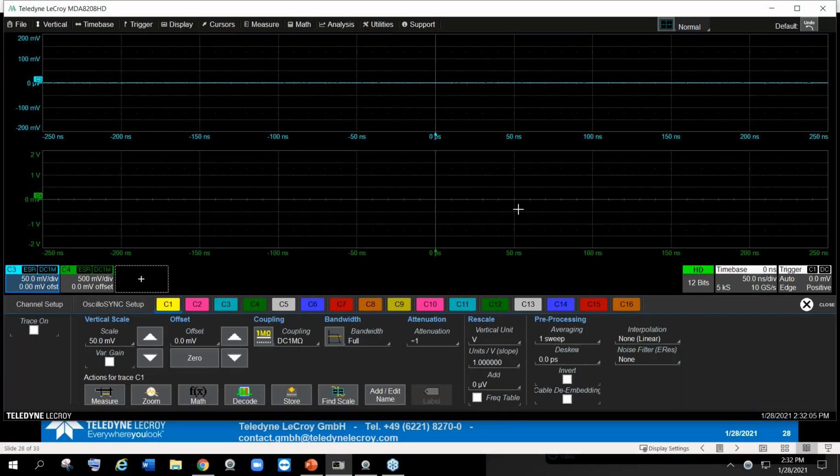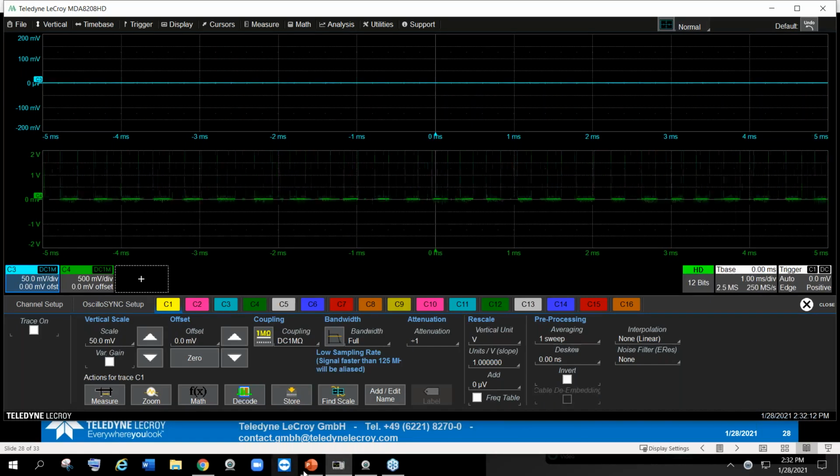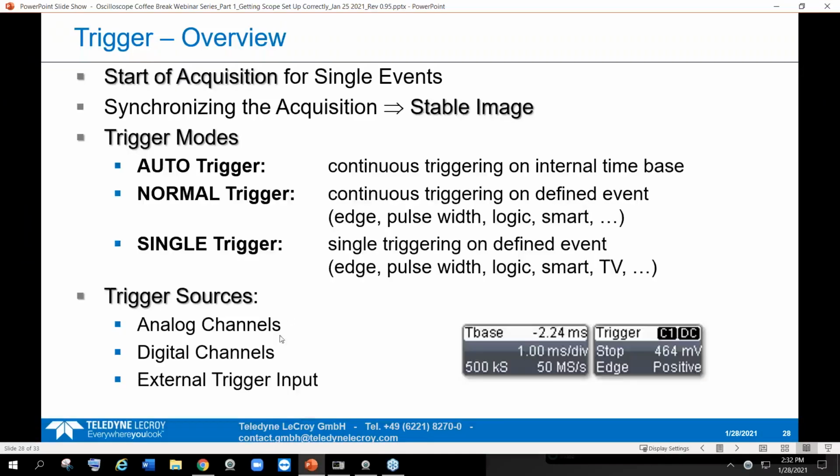And actually, I'm showing it now. Oscilloscopes have these things called auto, normal, and single shot triggering, and the scope's trigger circuit, which are called different things on different scopes. There's run and stop, and if you're in run, I think there's a setup for you to choose whether you want auto or normal.